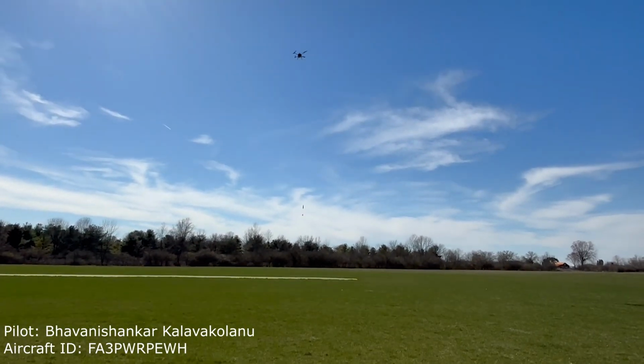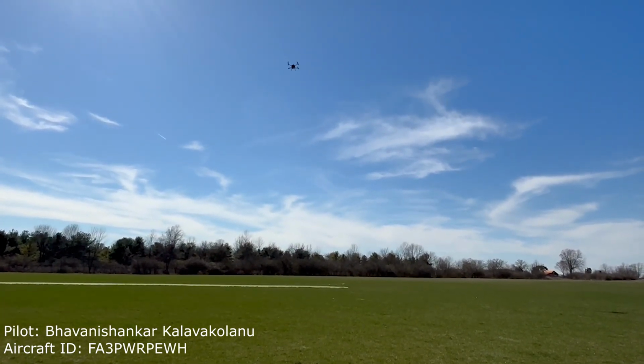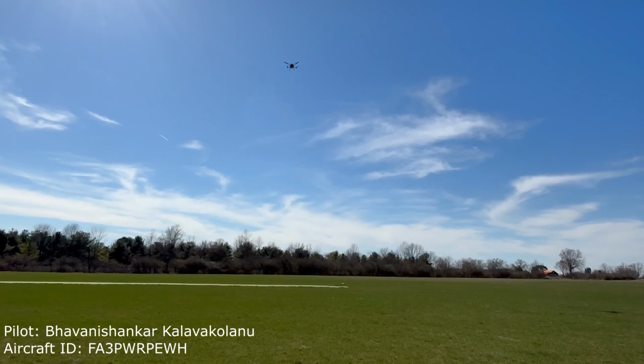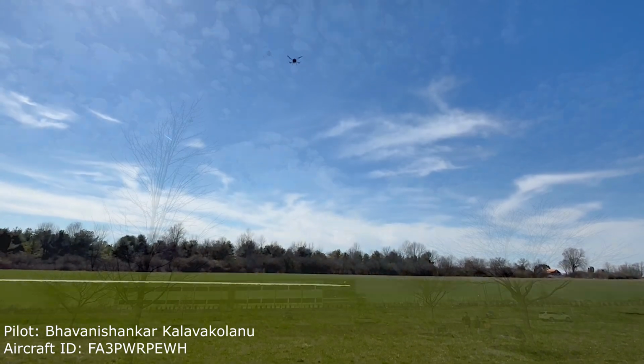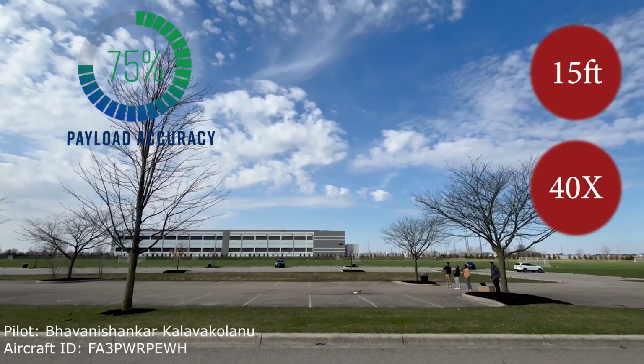When installed on our UAS system, the mechanism worked 100% of the time as well. However, depending on wind conditions, the bottle would land in various positions. After dropping 40 times, we had a 75% overall success rate, with the bottle on average landing 15 feet from the target.